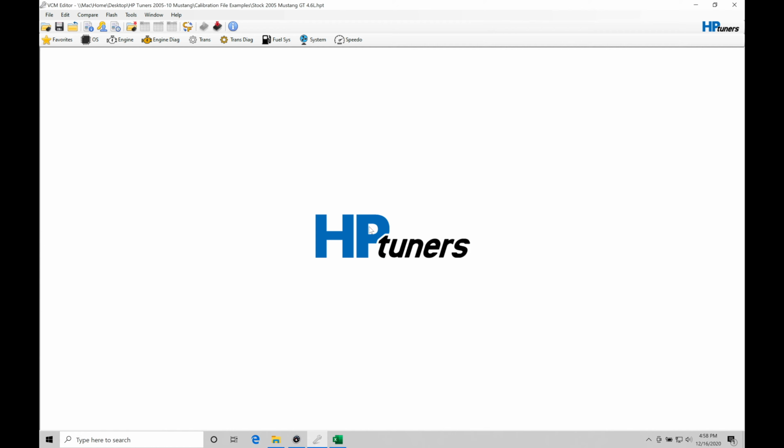We don't want to inherit any bad data or any tables that might be set up incorrectly when you're starting off in your tuning process. If someone already has tuned the car, we want to essentially put a reset button on the calibration file. So we want to again return it back to stock using the compare feature, copy and paste between your stock equivalent file and your file that you're working with, and then save it as a new file name. And then that's what we're going to be starting off with looking at in this video.